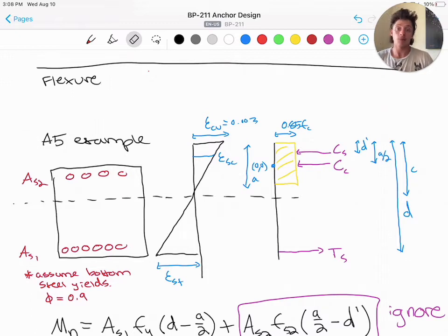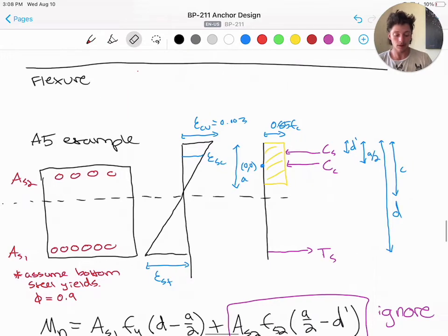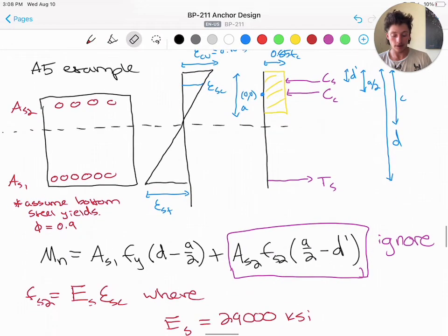But it is important to have this compression steel for a variety of reasons, such as temperature and shrinkage, and beams with a fixed end condition. Remember from earlier, when I drew the moment diagram for a fixed end condition, how the moment switches signs at the supports. So, like I've shown here, we ignore this,